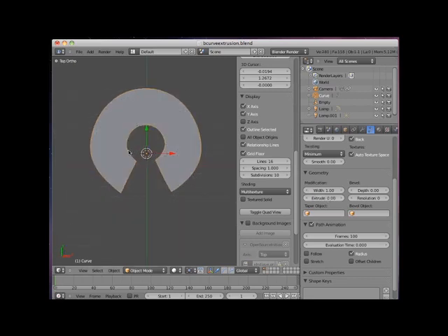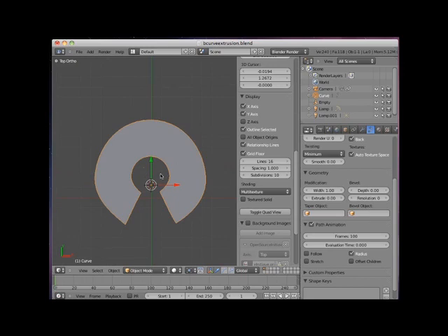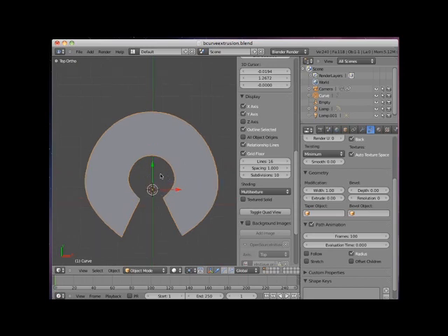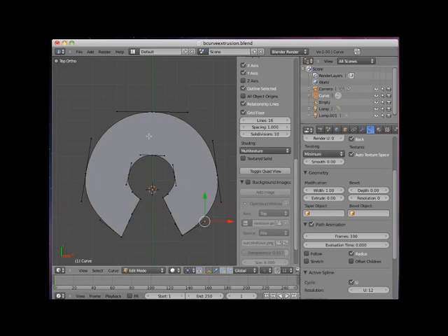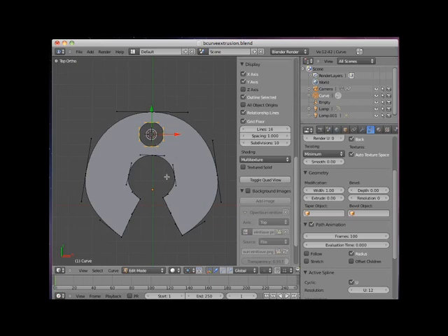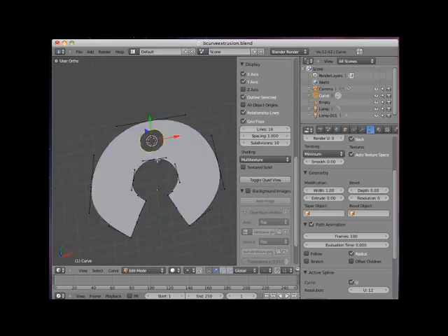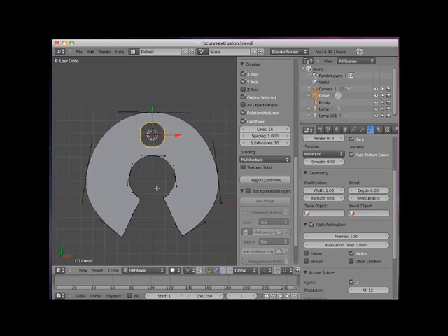One of the interesting characteristics of a curve object is that the surface generated by a closed 2D spline will exclude any other closed 2D spline within the same object. To demonstrate this, I'll tab into Edit mode, and while in Edit mode, I'll add a Bezier circle to the curve object. Note that the circle is cut out of the curved surface. I'll alter this shape a bit.